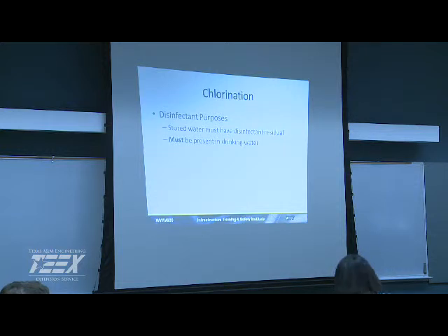What are y'all getting in from your source water? How much residual are they sending you? About 1.5, 1.7. Okay, so that's pretty good. And what do you get on the end of your system? About 1.2 to 1. So you're having real little degradation.